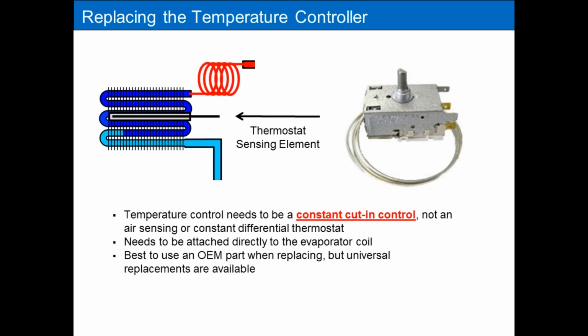It makes life a whole lot easier, and make sure you put the temperature sensor back in the same location that the original was at. Put it back in that well, which is not always easy, which is sometimes a chore all by itself. They don't make that easy, but that's the best approach.